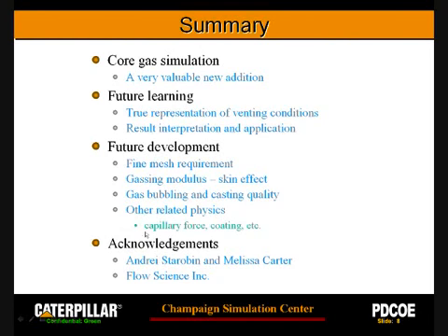If we can also consider some like the coating effects, capillary force forming, I think usually the model right now so far assumes if the gas pressure is higher than liquid pressure, then you form the bubble. We know when the bubble forms you also need to overcome a lot of these surface tension factors and other factors. I think if we can consider that, it's probably more realistic. So far, this model solution, I think, is always conservative. So it's a good thing, at least we have this tool.